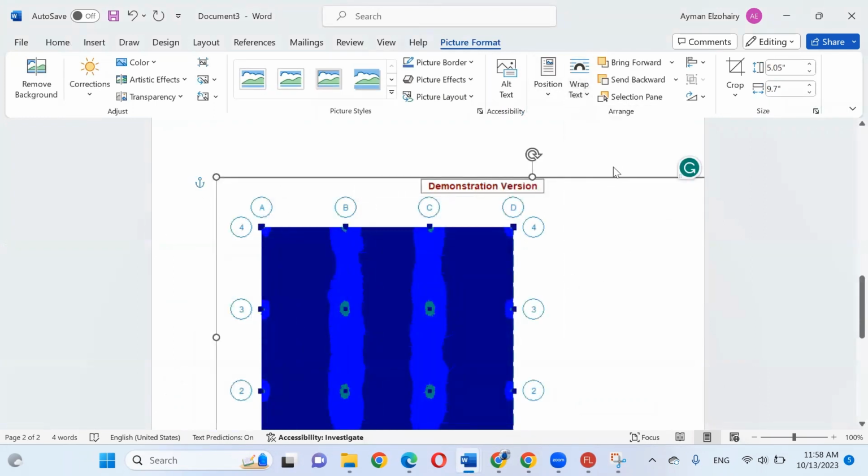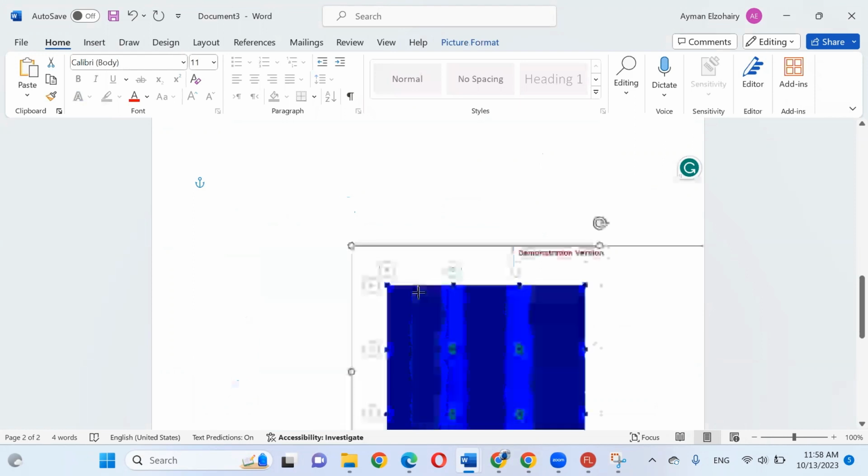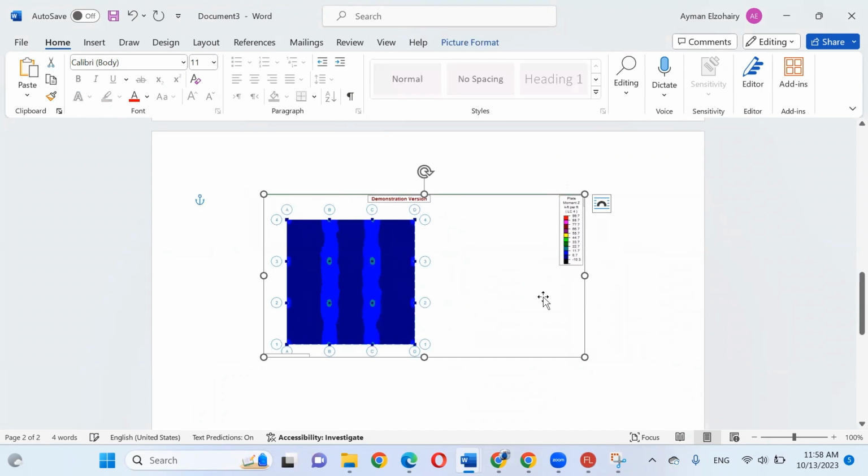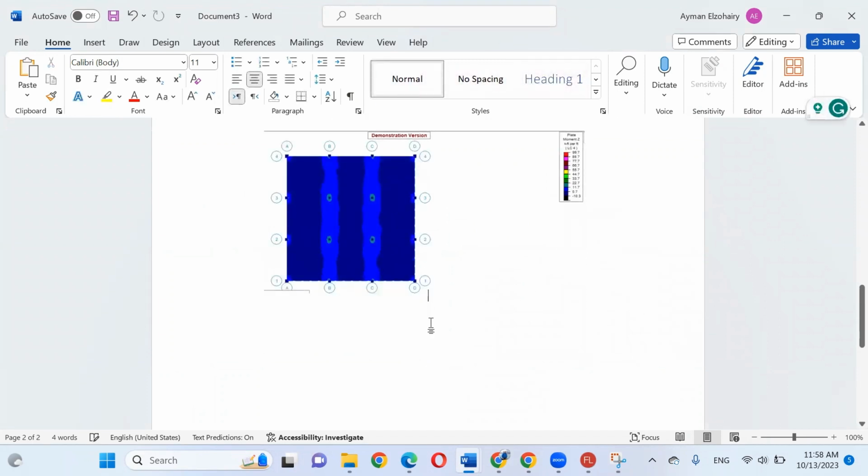Does that make sense? You can make it smaller, by the way. If you feel it's very big, you can make it smaller. And you can write here, this is MZ for steel rebars in horizontal directions. And the M ultimate from this one will be 11.7 kip-foot. And if you would like, go ahead and make your design.